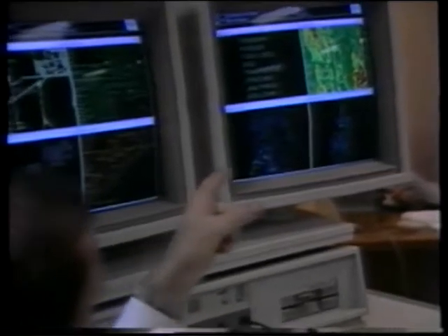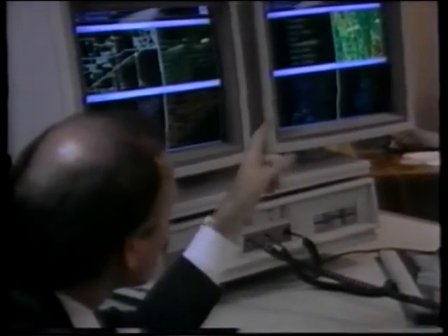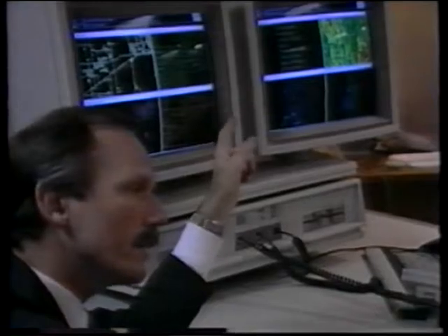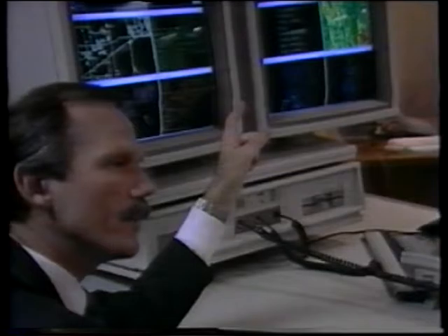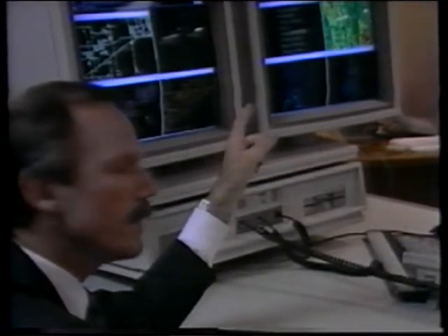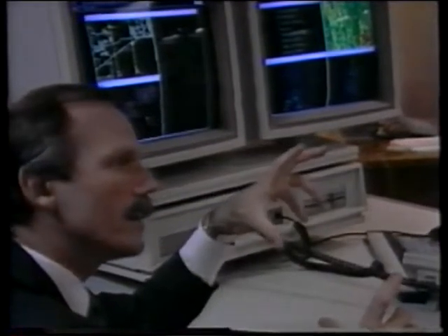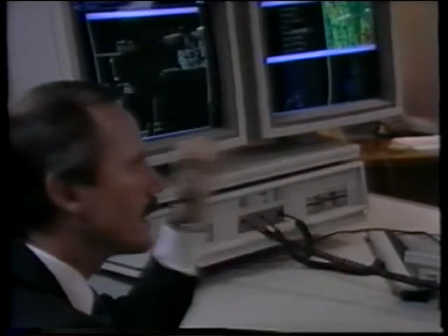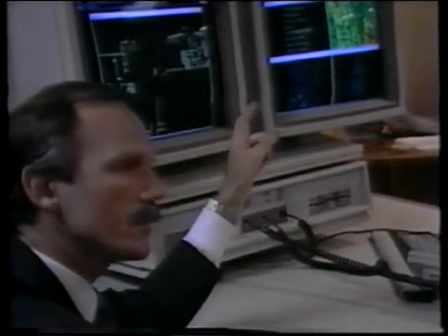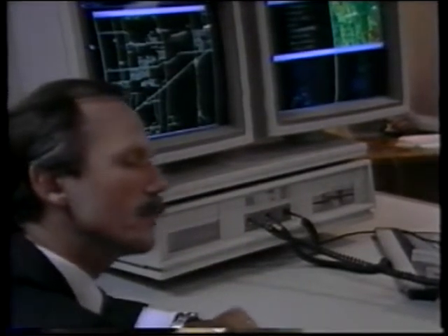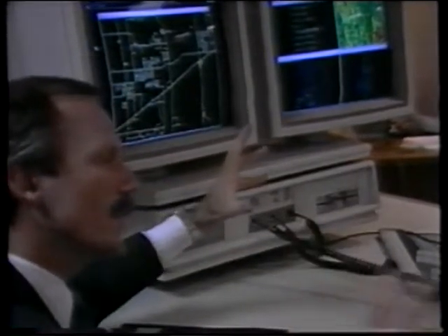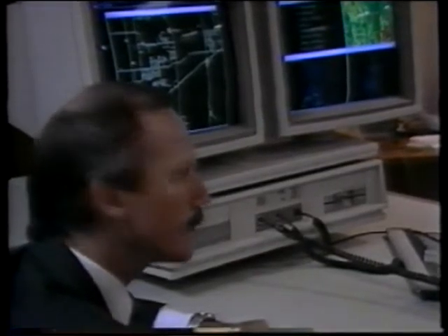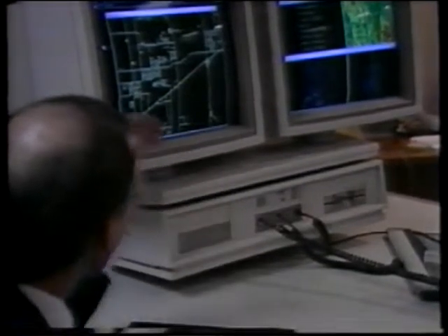So what we'll do, as soon as that grid model finishes painting, is take that grid model. Right now, each grid cell in that grid array has an assigned average slope value. We can take that and generate from it a polygon, in essence, of all the grid cells combined into one polygon that are of a single slope value. So rather than deal with a large array of numbers with each grid cell or each XY location having a slope value, we can simply deal with one large polygon: this is the area of 18% slope, this is the area of 0.2% slope. All right, let's go back.